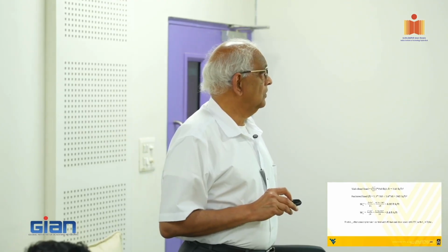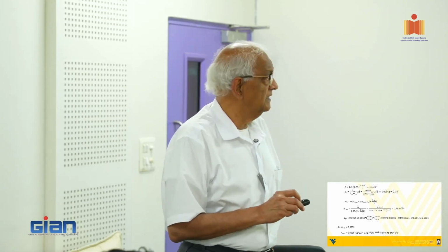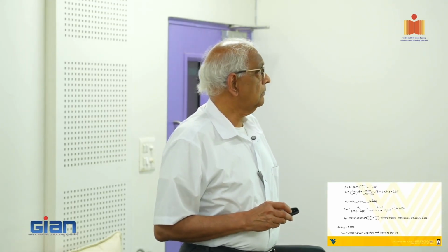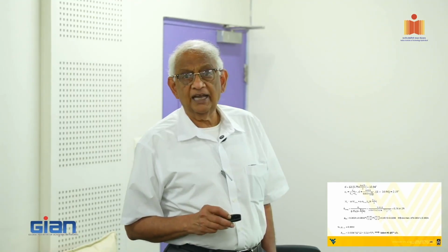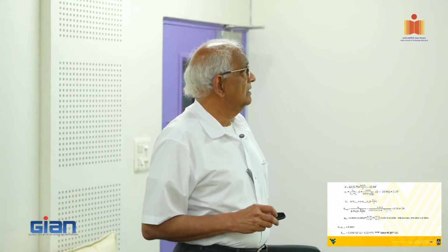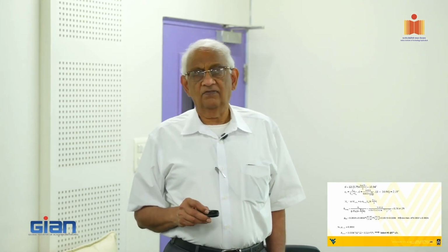Okay, so if you assume a tension control, you don't have to. That's entirely up to you as a designer. Then there's a clear cover, and F sub FU we already determined. So if my D value is 12 inches is the total depth, and you subtract the clear cover as well as half of the diameter of the rebar.